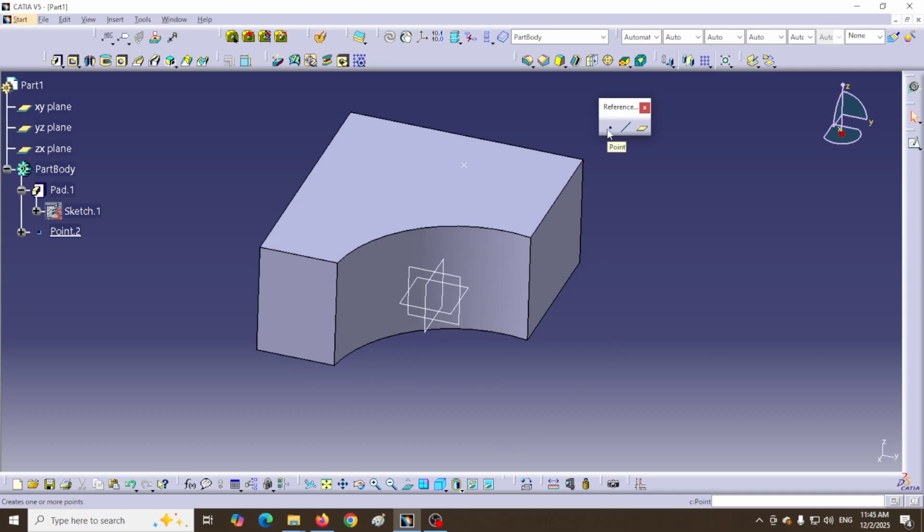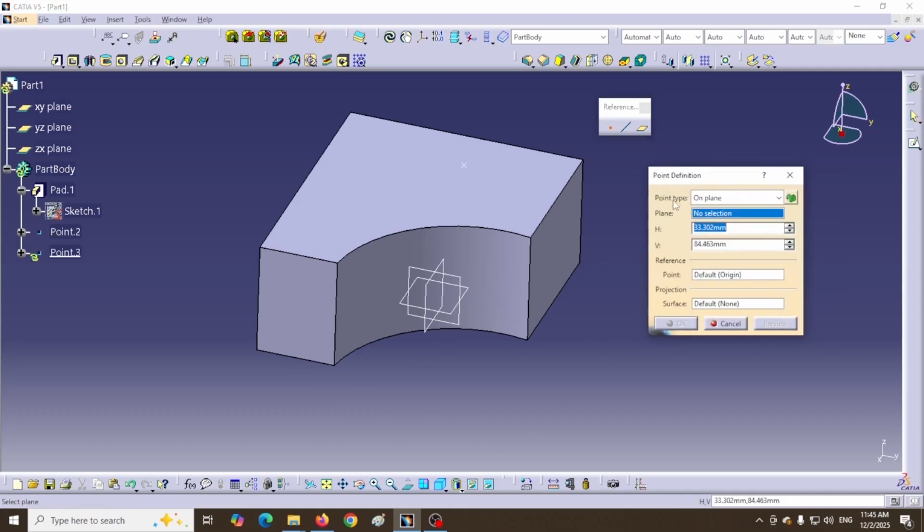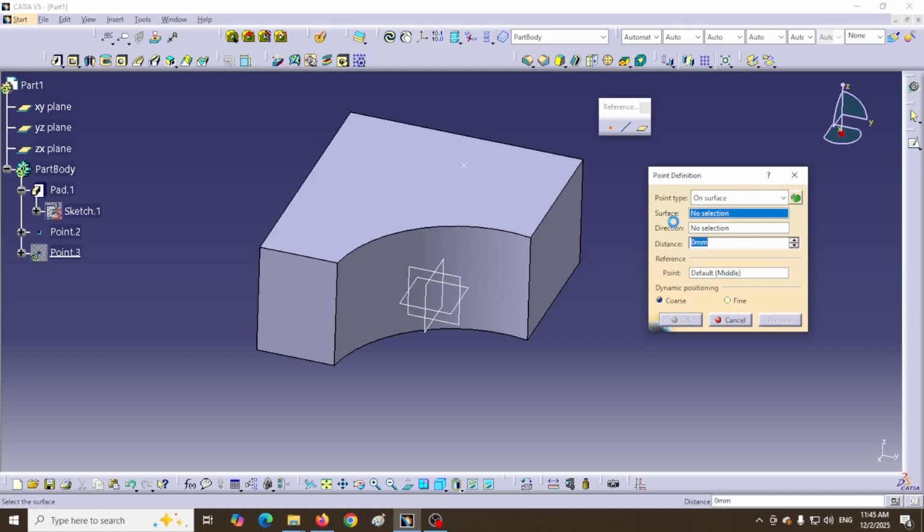I click on the point tool again. I set the point placement mode to on surface. In this software, surface refers to non-flat surfaces. Look, the settings window changed according to this mode. In the framework in front of surface, which is currently blue, we must introduce a curved surface. I click on the curved surface of the existing volume. The surface became selected.